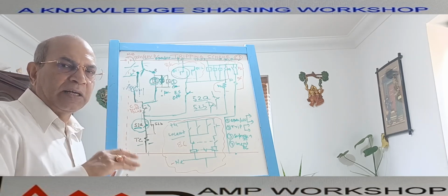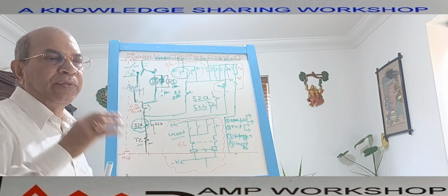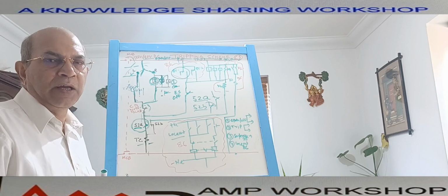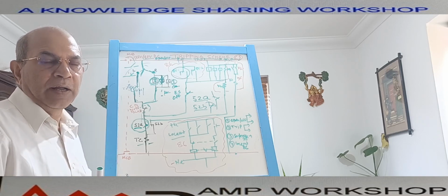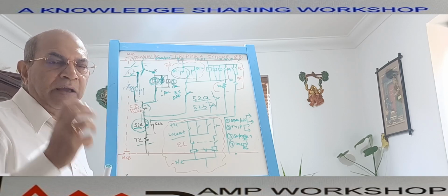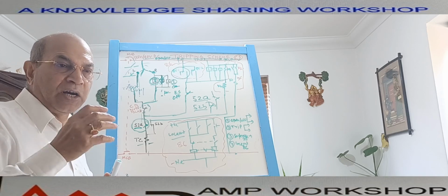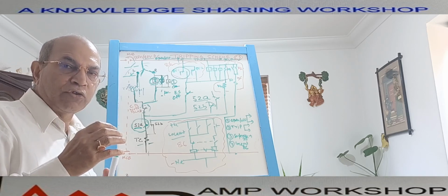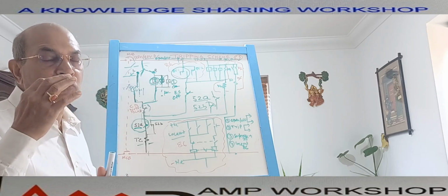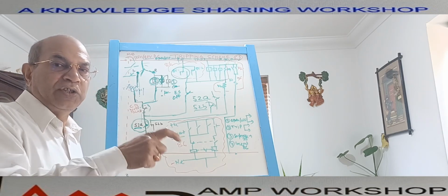Sometimes a digital relay does not have all this provision. That's why we have a special type of relay which is called the lockout relay. That relay is a very rugged relay. It has a high output current rating, and it has a feature that once the lockout relay operates, it will not reset until you manually reset it.